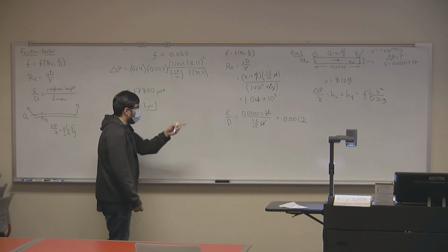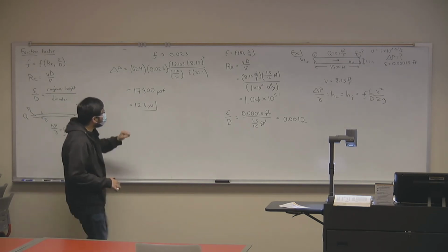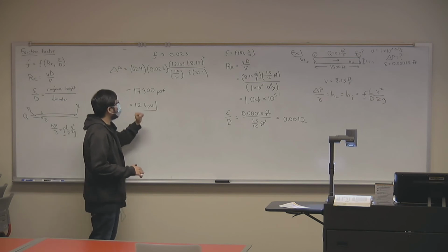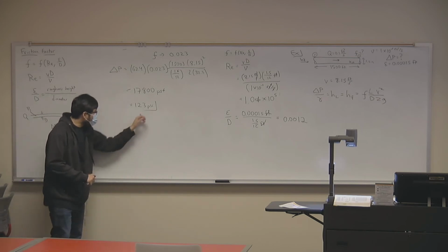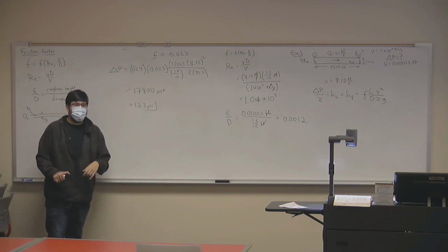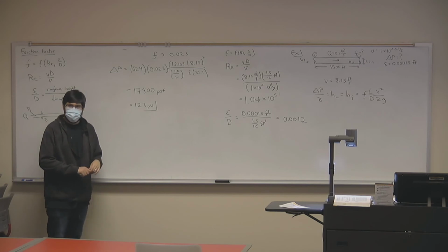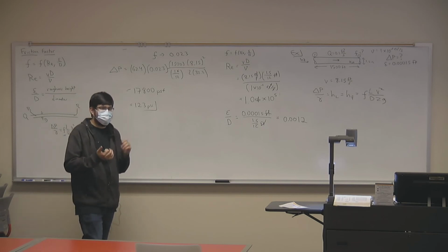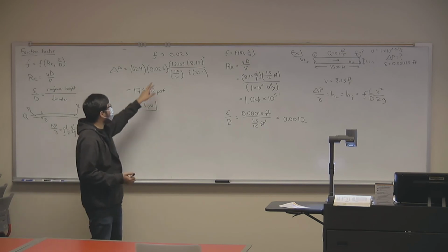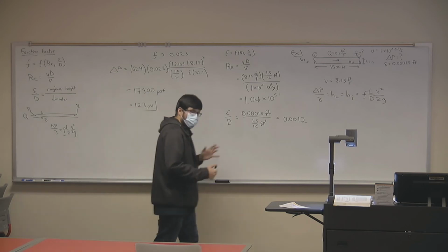Okay. Earlier we had 107 PSI, right? So only a 0.003 difference in the friction factor results in about 15 PSI difference in pressure. 15 PSI is not a small number of pressure, right? Yeah, the tires in your car have pressures of 30 already. So it is a sizable difference compared to the small amount of difference in friction factor, okay? Let's leave it there. Go ahead.